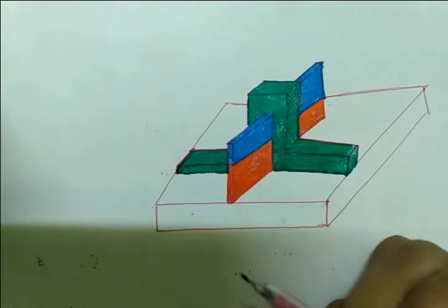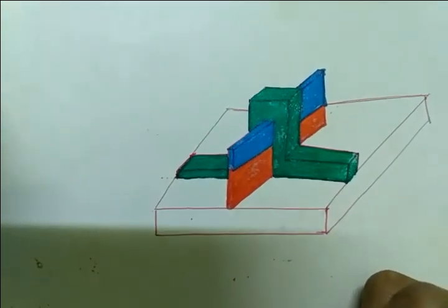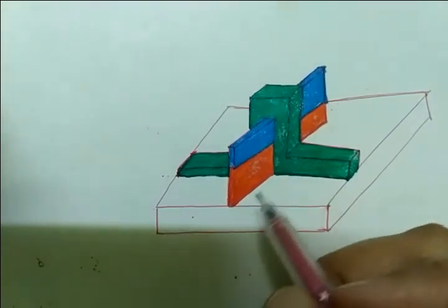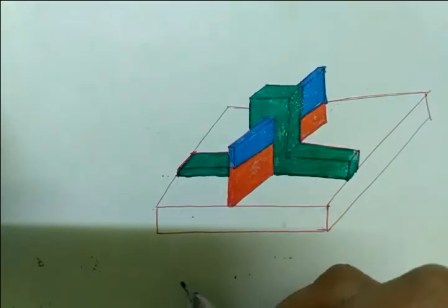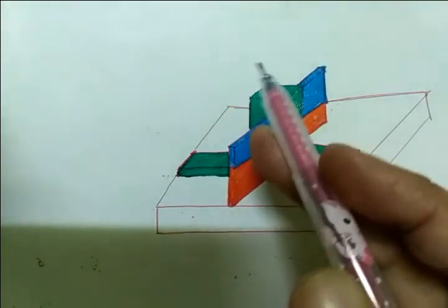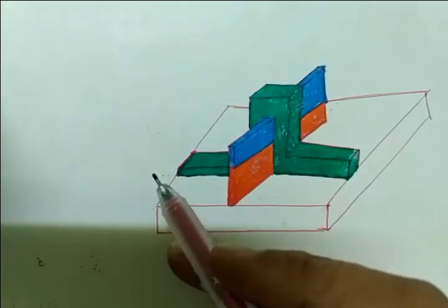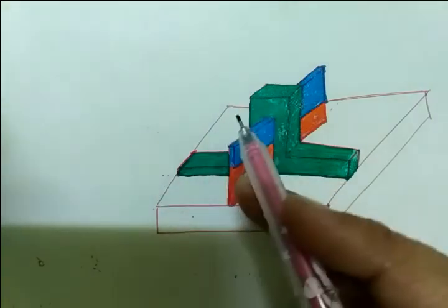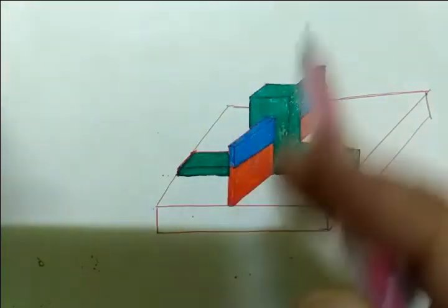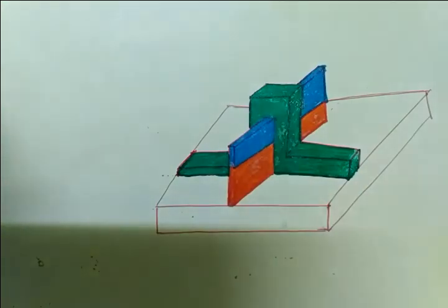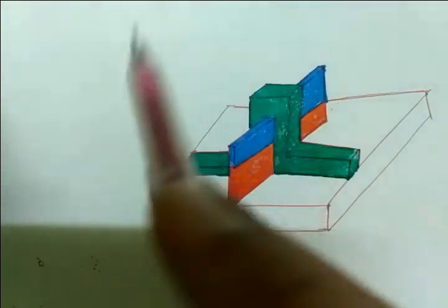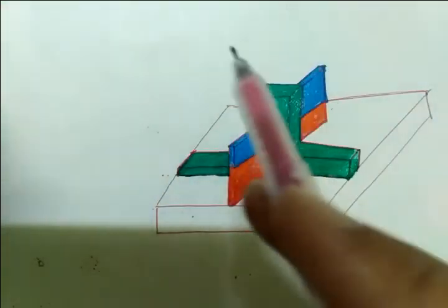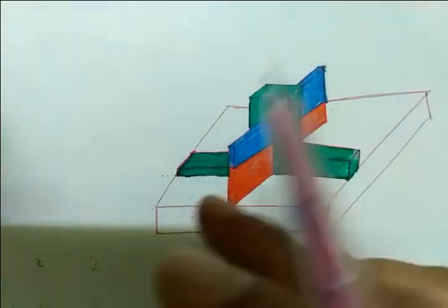So this is your FinFET structure. The major challenges faced in scaling of MOSFET are the subthreshold leakage and drain-induced barrier lowering, which are effects of the reduction in channel length. FinFET, as a variant of the MOSFET, is a structure where the source and drain regions are grown over a layer of insulator.